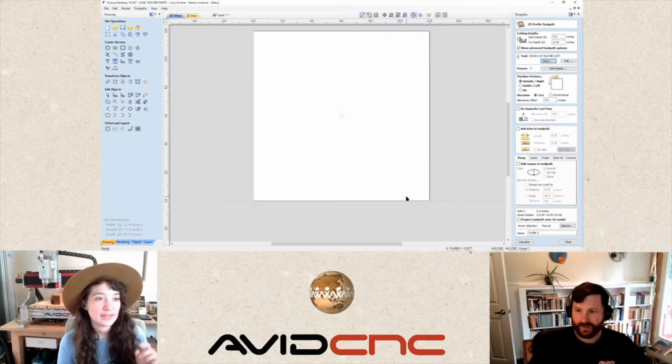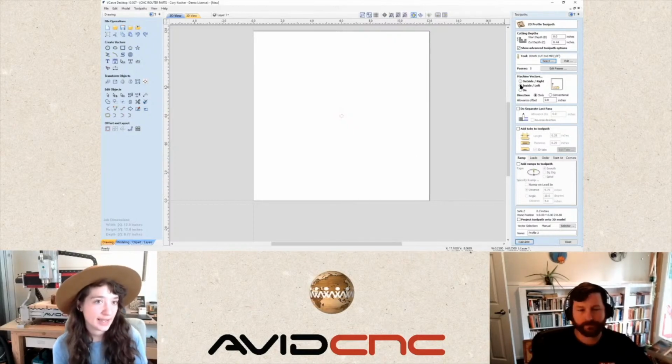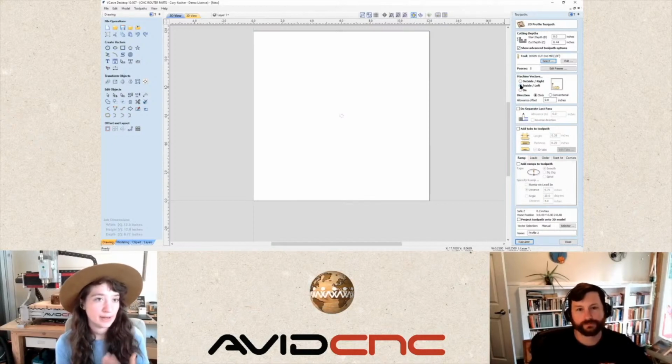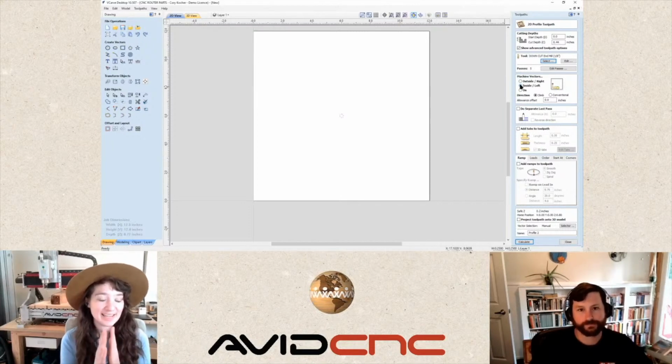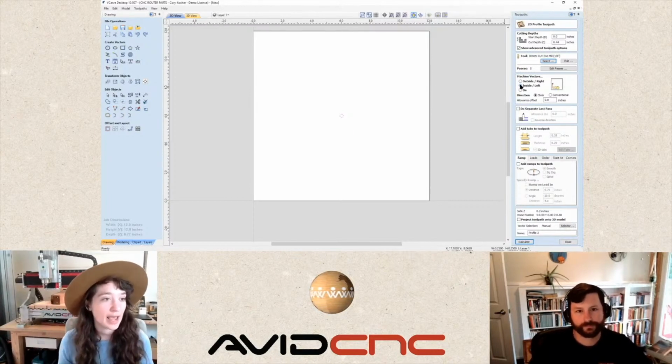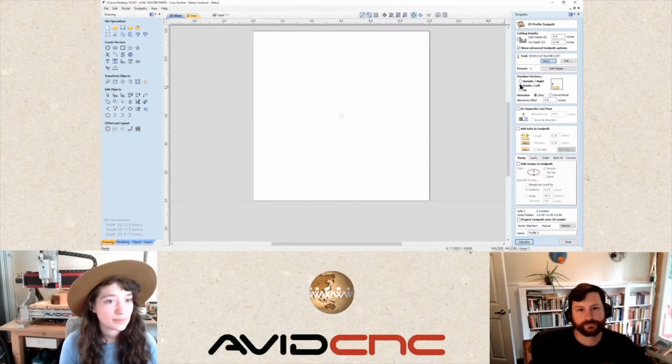What I do like about this is that you've selected a 1/8 inch bit for a 1/4 inch hole, so it's still the radius of the hole. That way, when it goes around, it's not leaving a cylinder inside that will break off and somehow get jammed between the bit and the wall as it's lifting up and out later on. So it's still essentially accomplishing a pocket, but it will give you that helix effect.